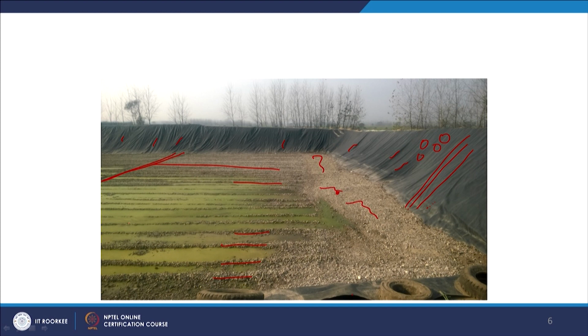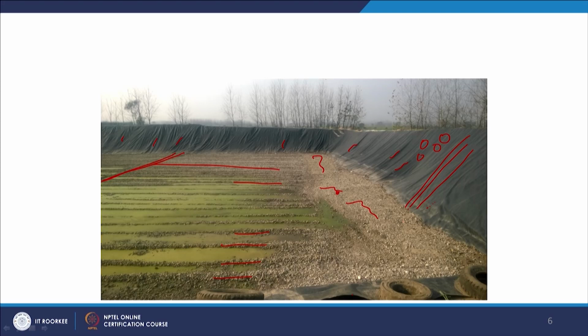And obviously, as you see, it is not homogeneous. The picture was taken during rainfall, but again it is not homogeneous, or it was still under construction. So here you have the leachate collection system and the gravel and sand, but the consistency and the homogeneity of the system is missing. And then rather than maintaining the slope such that all these layers can be taken up along the sides, they only took up the relevant HDPE membrane.